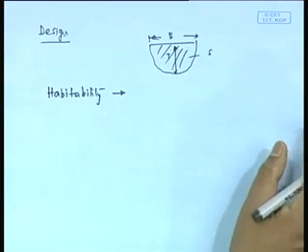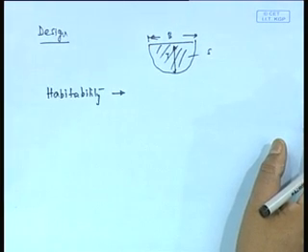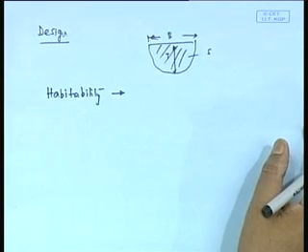Of course, you know what habitability is. There should be certain criteria, certain limits of motions, that make it habitable. For example, if accelerations exceed a certain amount, you find it very uncomfortable, which actually happens quite often, especially if the natural periods are low. When natural periods are low, then frequency is high, and then acceleration becomes much higher.